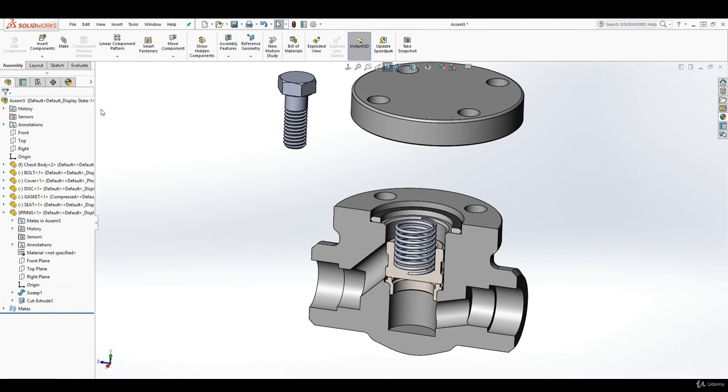What we did is we made the planes together. That is what we were discussing about design intent, because sometimes it depends on how your part is going to build in the assembly. Because of the way we built this spring, the planes in the model are on the same planes as the assembly, so it makes it easier for us to just mate the planes together.